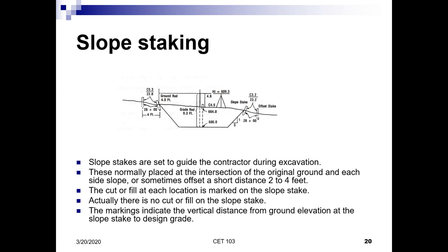With that information, we could then calculate the point at which the existing ground and the finished grade intersect. The unfortunate or the hard part about this process is that it's sort of a trial and error, hit or miss process, because the ground is constantly changing. So therefore, that particular point has to have a few trial and error type indications to find it. Let me head on to the next slide and I'll explain further.